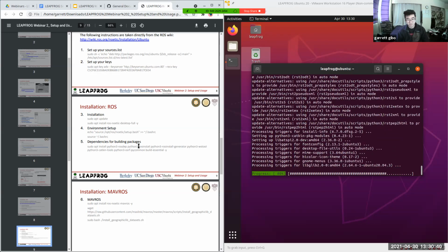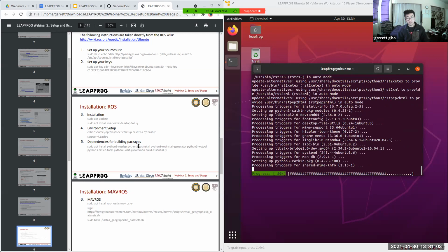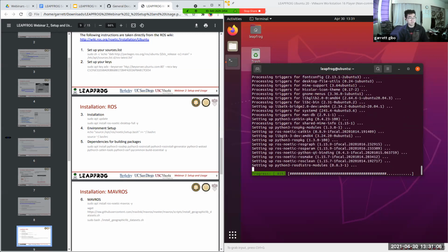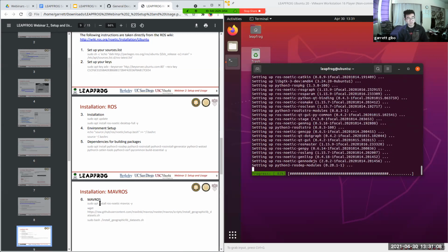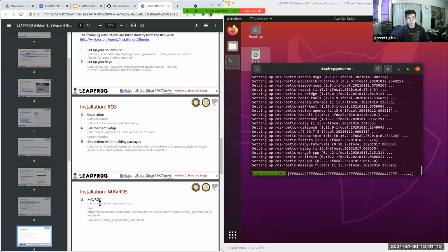In addition, when you are developing your own navigation algorithms, it can be difficult to integrate this directly into the PX4 system. So what ROS allows you to do is develop this however you want, separately from it. You have more flexibility in how you design the architecture of your navigation and what languages you can use. And then as long as you communicate over ROS and also MavROS, that'll allow you to integrate your navigation code, which is completely separate, with the actual PX4 simulation environment.